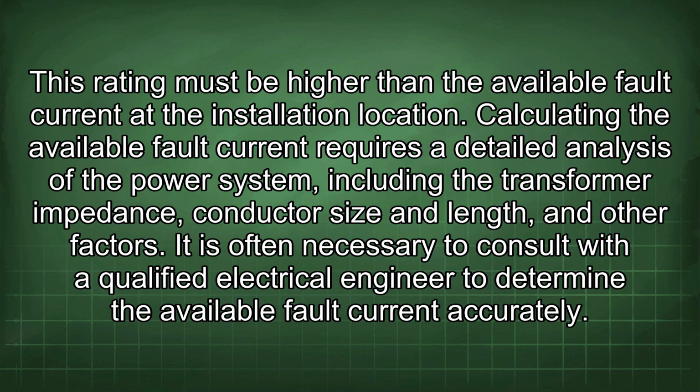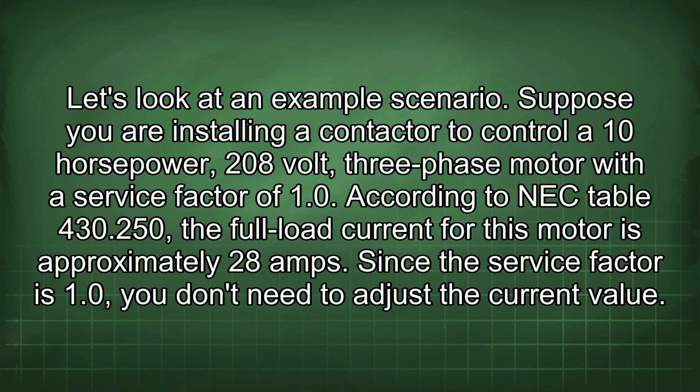Calculating the available fault current requires a detailed analysis of the power system, including the transformer impedance, conductor size and length, and other factors. It is often necessary to consult with a qualified electrical engineer to determine the available fault current accurately. Let's look at an example scenario.